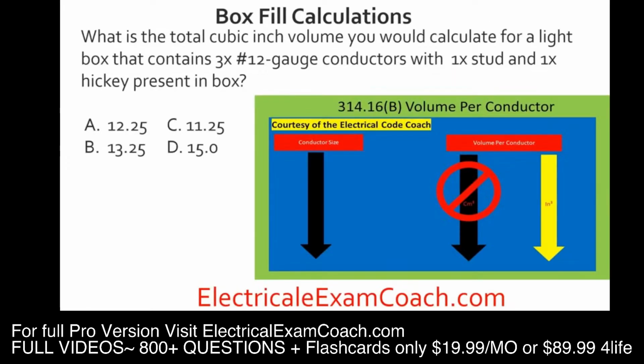What is the total cubic inch volume you would calculate for a light box that contains 3 12-gauge conductors with 1 stud and 1 hickey present in the box? For this one, we're going to go to table 314.16(B). We know that each 12 is 2.25 cubic inches. Now let's count our conductors. We know that we have the 3 number 12s originally, but now we have to deal with the studs and the hickeys. Our code states that for each stud and each hickey, they count as 1 each based off the largest conductor that's in the box.